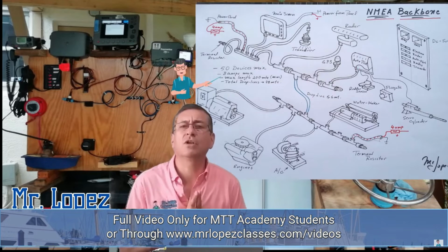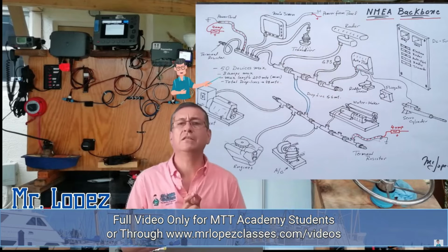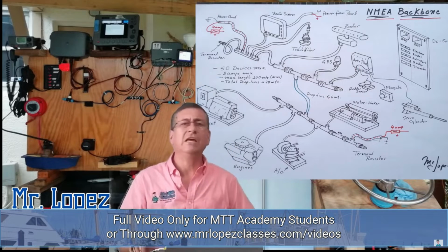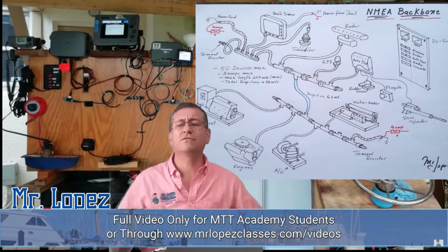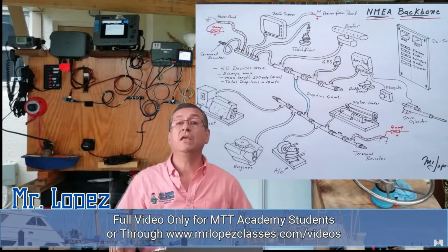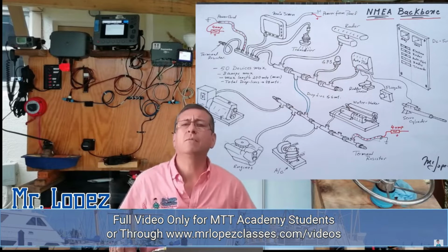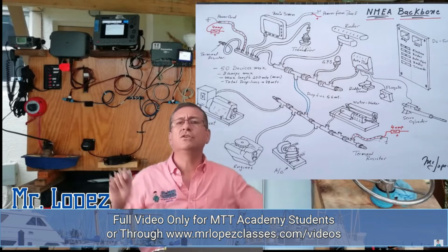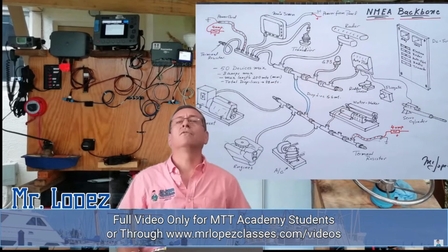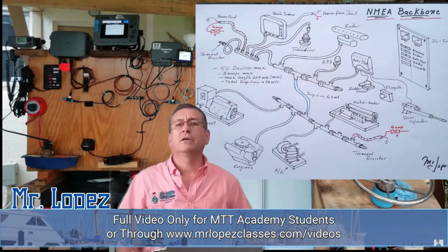How much is the maximum amount of devices recommended? Yes, no more than 50. How much is the maximum total distance of the backbone? Depends on the cable. Remember, for mini or for micro. For mini cables, the maximum distance is 250 meters. For micro cables, 100 meters.